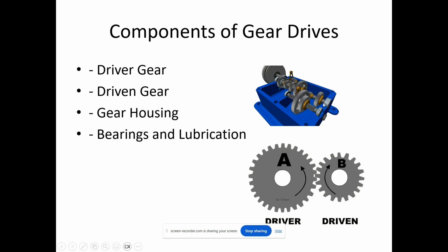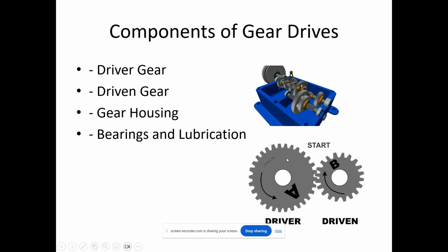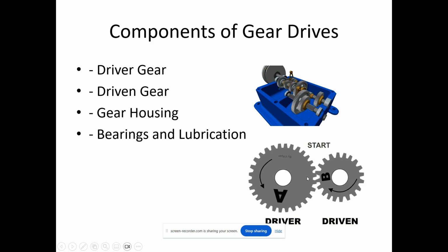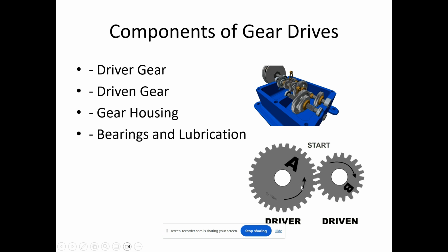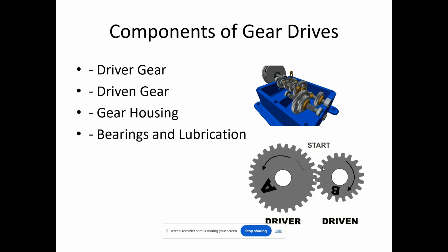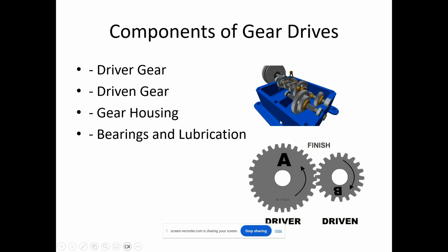As you can see here in this gearbox or in just this simple sketching, we have a driver gear, gear A, and a driven gear, gear B. And you can see that when only two gears are linked, the motion of the gears goes in opposite direction, right? So it's not the same as belt. With belt, uliona connect a pulley to another pulley, two pulleys, the direction of motion or transmission of power or torque is in the same direction. But here it's reversed.